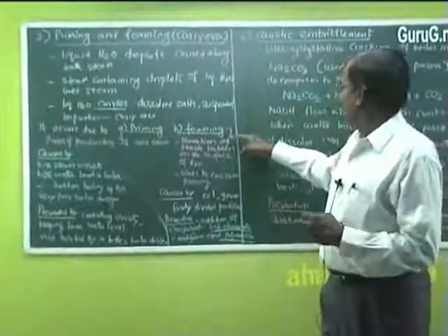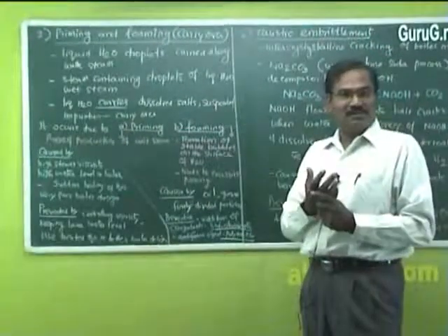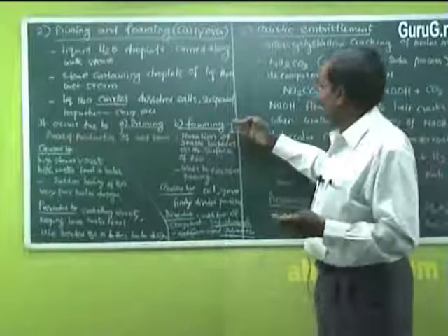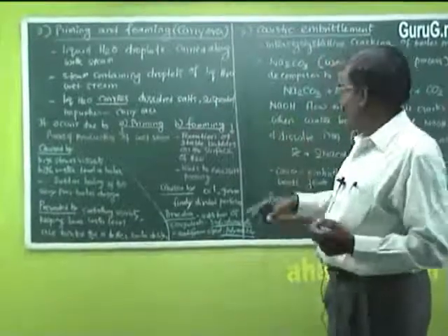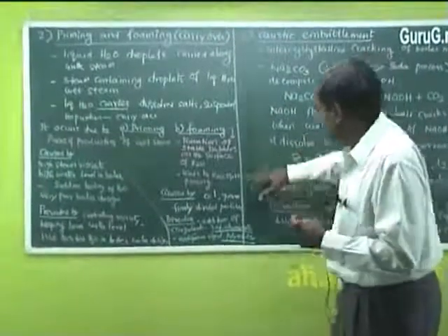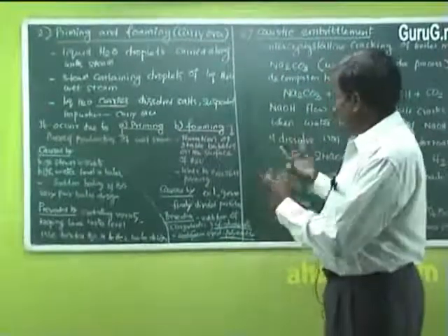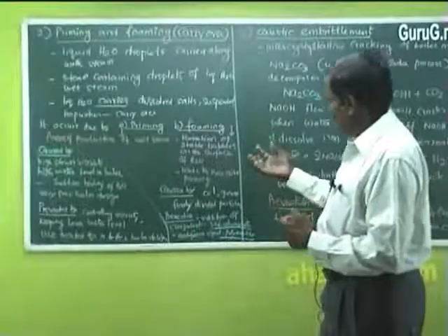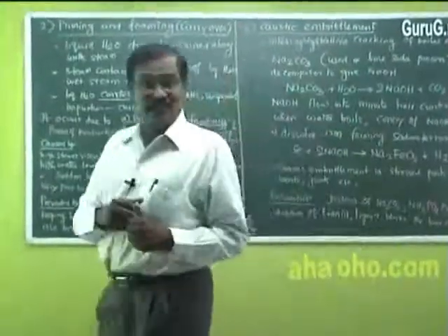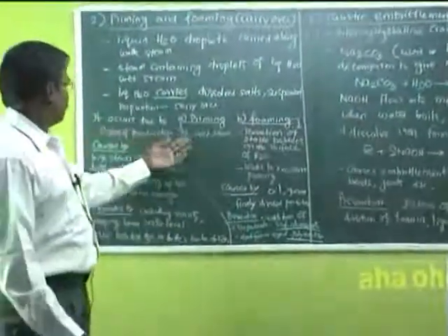see that term foam, is the formation of stable bubbles. When water boils, you can see the bubbles on the surface. Normally when oil boils, there will be some bubbles on the surface. Similarly, foaming is the formation of stable bubbles on the surface of water. Since we are getting such bubbles, it is enhancing the rate of priming. These bubbles tend to go with the steam, so priming is enhanced. Now let us concentrate on priming. Priming, I specified earlier, is the process of production of wet steam.